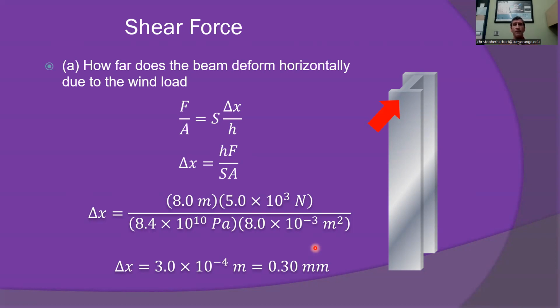But of course, if the building is moving, and if you've ever been in a high rise during a significant amount of wind, you can physically feel the building moving back and forth. And again, because glass is a very brittle material, sometimes you need elastic spacers. You need rubber spacers to not only allow the glass to thermally expand and contract, but also allow the frame to flex a little bit for the windows themselves.